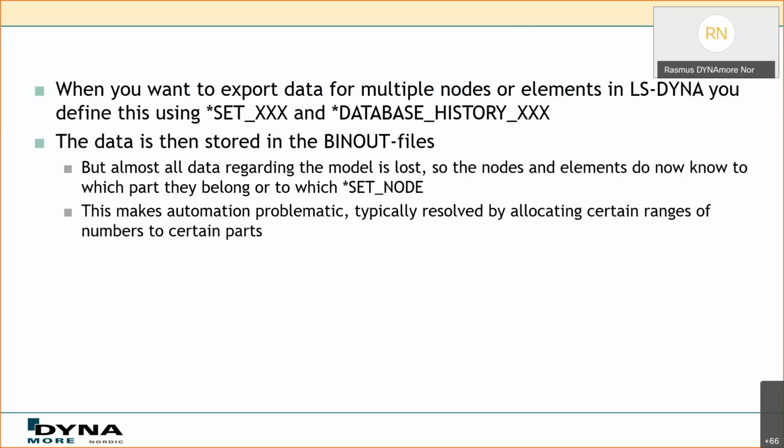So, about the binout file, or the binout format, a bit. When you want to export data for multiple nodes or elements in LS-DYNA, you typically define this using star set and the database history of that set. So say you want to export the data for a few hundred nodes, for example, you typically create a set of those nodes, and then you export them using the database history. And the same can be done with, for example, elements. You want to have some high resolution in one area, for example, and then you export it based